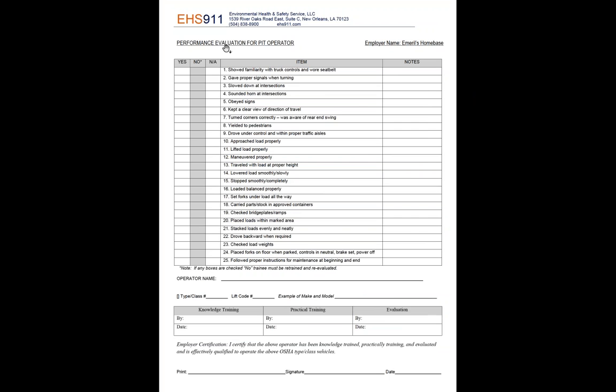Basically, this is how we do our evaluation form. I'm happy to send it. Send me an email if you need it, okay? And if you notice on here, these are the 25 items that are either recommended or required by OSHA. If it's non-applicable, we'll just put non-applicable. If it's not elevated platforms where there's a loading dock, we often don't have bridge plates. So ramps or bridge plates will often be checked NA. Everything else, or just about everything else, we have to check yes.